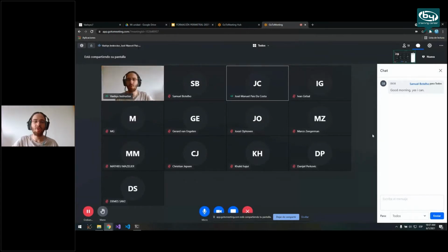Whatever you want, because in thermal imaging we work the same way as in visual imaging. So the system will work the same way, and the rates will be more or less similar. Of course, in thermal imaging it's easier to detect people because the contrast is really good, and we have more information to distinguish an object from the background.